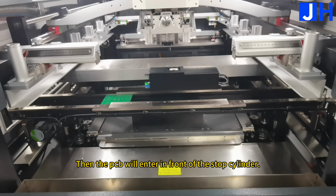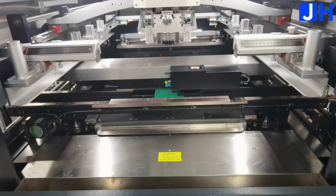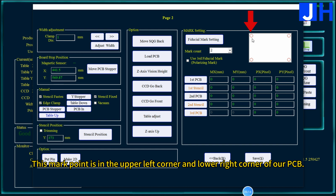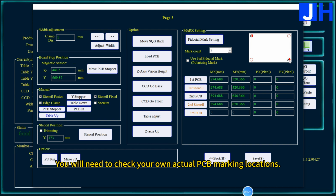Then the PCB will enter in front of the stop cylinder. After the PCB is loaded and reaches the anchor point, we start making PCB marks. Let's check where the PCB mark is located. This marking point is in the upper left corner and lower right corner of our PCB, so we click on these 2 points. You will need to check your own actual PCB marking locations.